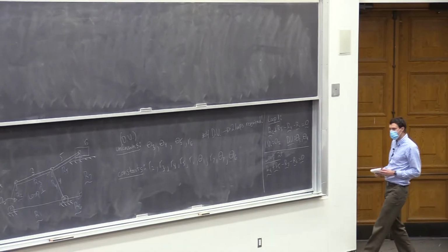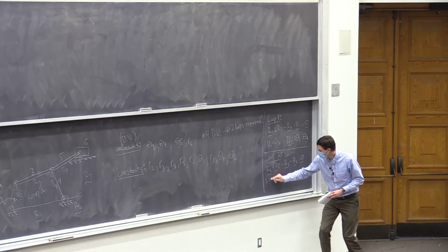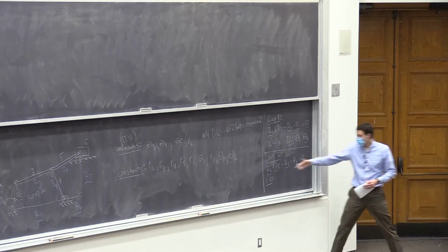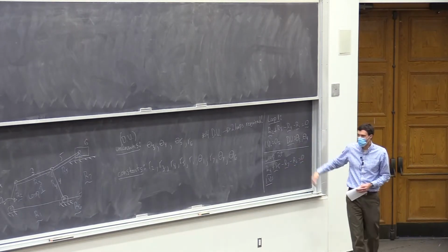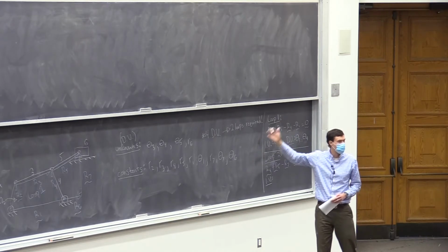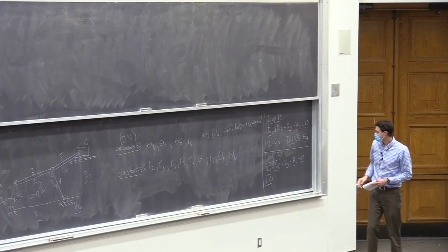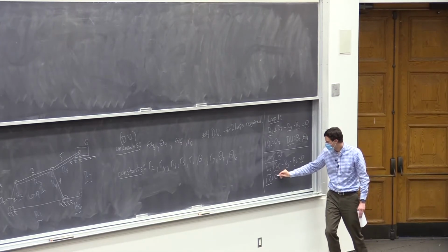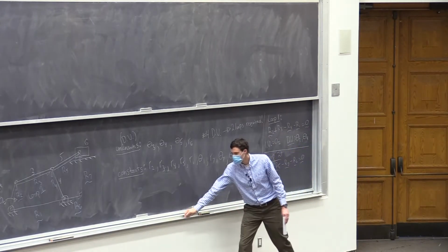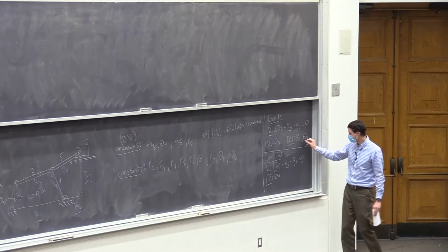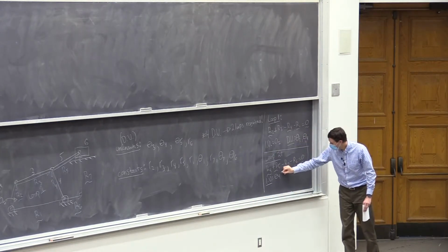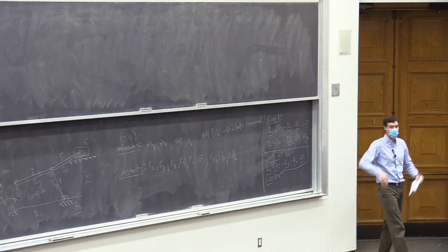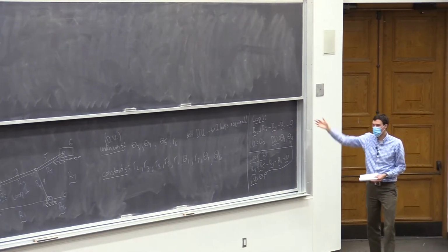Okay, and this has an independent variable of what? What's the input to this one? The input needs to be one of the outputs from our previous loop. So they share R4, right? They share R4. So the independent variable, or the input to loop 2, is theta 4. And that actually gets plugged right in from loop 1 into loop 2. And that's a good thing. That's how we can progress through our solution.